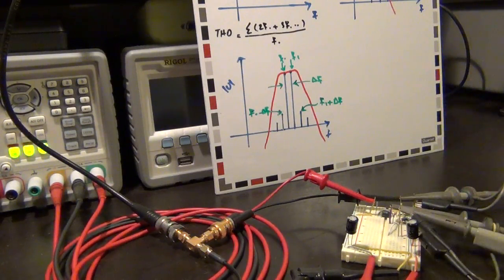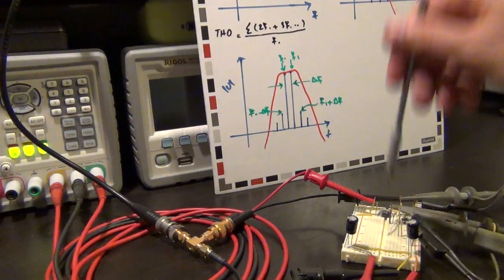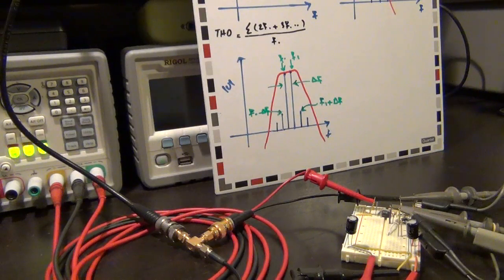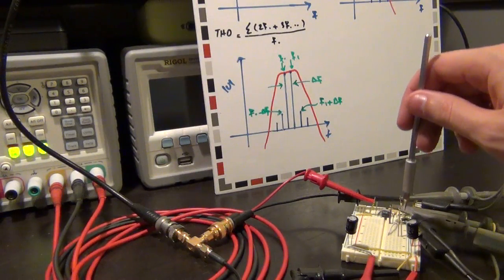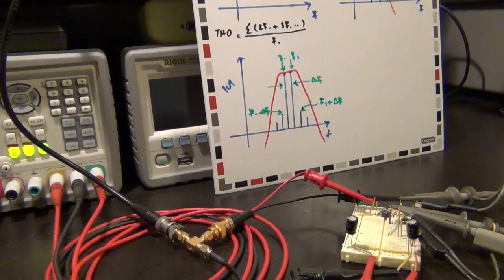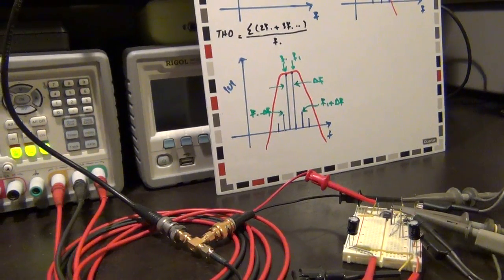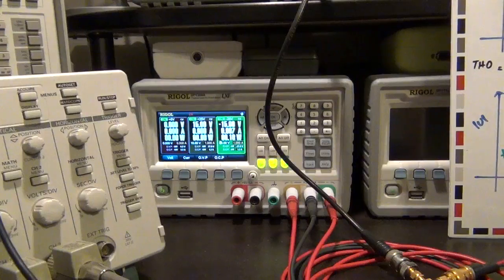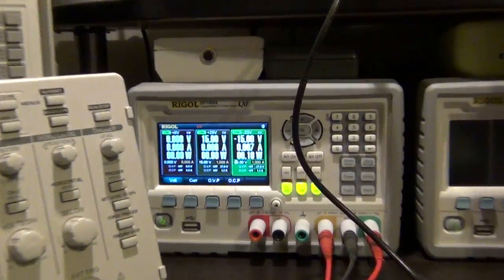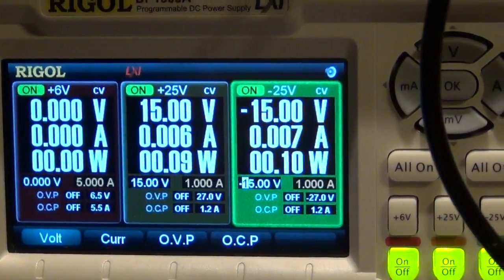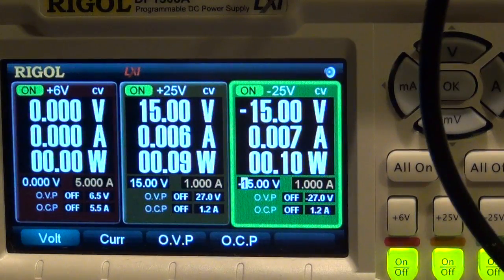But in terms of circuit elements, we could demonstrate all of these nonlinearity effects and even a two-tone test by using simply diodes and resistors. And don't forget to solve the puzzle of why the two diodes eliminated the second order harmonic in our first test. Just one other minor note. I mentioned that I have an op-amp in the front, and I'm biasing the op-amp using plus and minus 15 volts, which is much higher than the input signal that I'm applying to it, and the op-amp has a gain of 1. So this way I can make sure that my op-amp is not adding any nonlinearity.